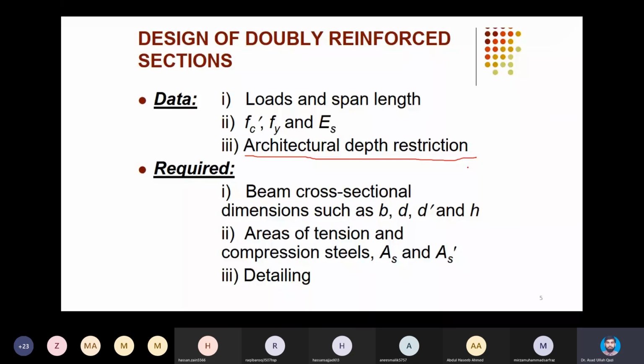So all this will actually be your responsibility. As a structural engineer, you have to decide the structural system, whether it will be a slab system one way or two way, whether you will go with the primary beams only, or on the primary beams you will put some secondary beams, and primary beams will act as spandrel beams for the secondary beams.